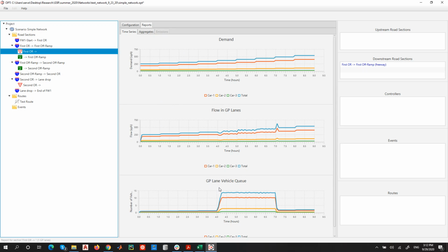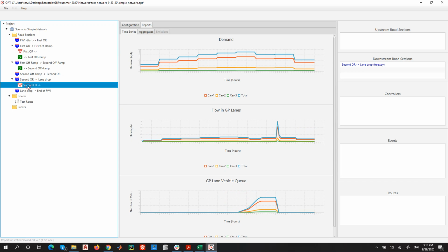Here we can see the queue on the ramp, and here you can see the flow as it was set. Our ramp meter was set from 4, so we can see here it was reduced at the rate that we set, but then the queue override hits, and we have this phenomenon. Here, where we didn't introduce a queue override, it was more consistent, at the rate that we set it. However, due to the lack of the queue override, we have an increase in the number of vehicles.